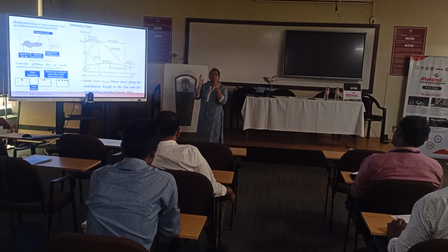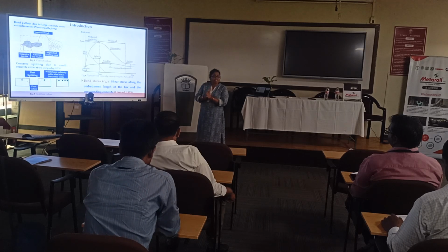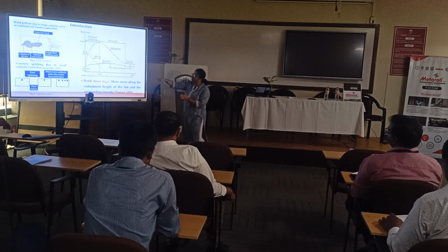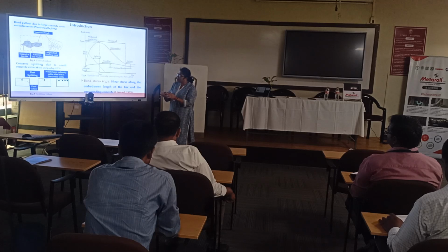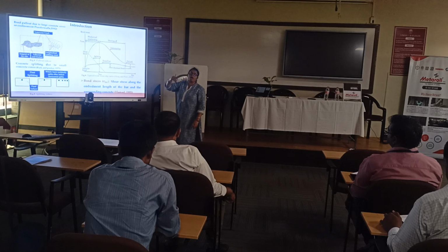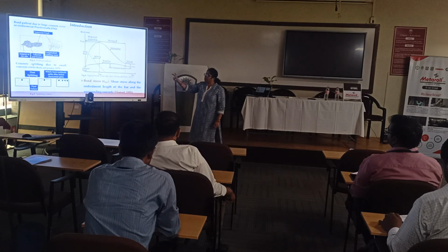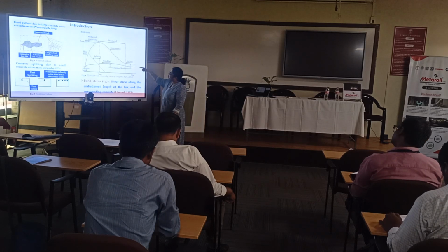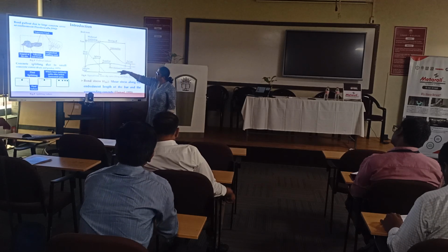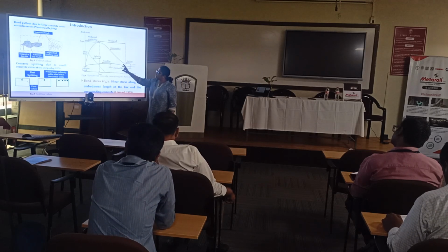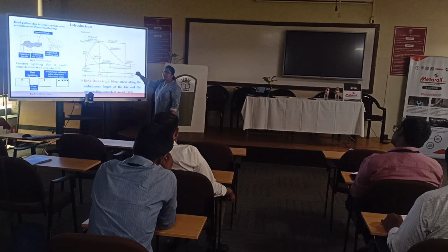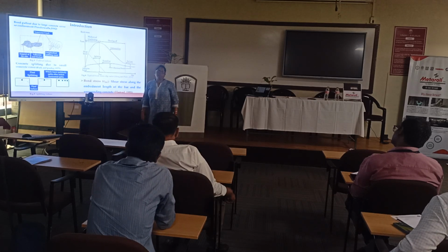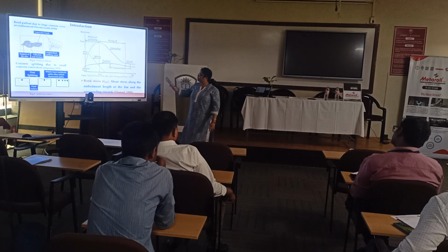First thing. Second thing, at what point the slip occurs. Once the slip occurs, the concrete surrounding the steel gets crushed. Then it will propagate gradually so that it can make a large crack, so that the cover comes out. Having said that, this splitting and the cover coming out is dangerous. Now, if you look at the different changes in slip versus shear stress, the deformed HYSD bar and the rounded MS steel bar have a very different form of curve when we talk about stress versus slip.